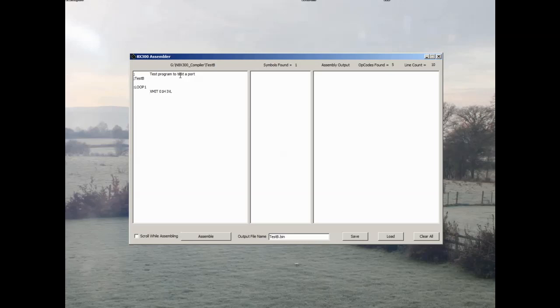So we want to send a value, again using XMIT. Just for the test we'll send, for example, 03, and then where to send it to and how many bits to actually send. So again, just an arbitrary value. If you're doing a real system, you would of course need to make sure you're sending the right number of bits and rotating them correctly, etc. So that sets up the address.